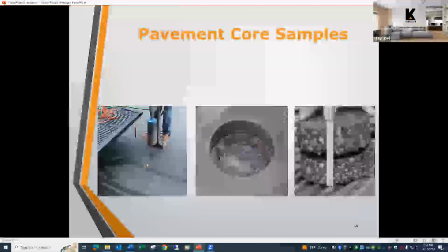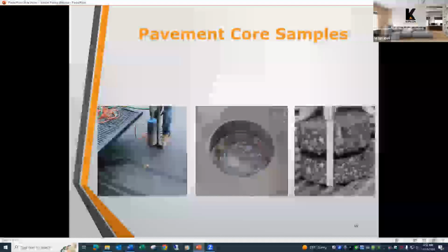Usually, to properly do that, the contractor should make any pavement repairs to the base course. They may want to scarify some areas of the base course just so they get proper adhesion, and put down tack coat. We'll see what that is later. It's kind of a sticky glue between the base course and the top course, and then they can put the new top course on.